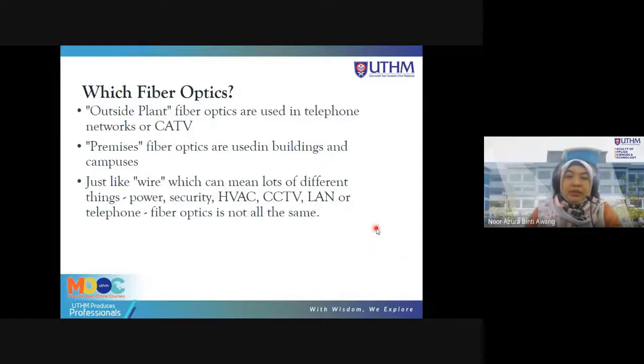So how do we install the fiber optic? Fiber is harder to install than a 100 megabit per second copper Ethernet cable, but fiber is much faster, so the infrastructure will not need to be upgraded so soon. Gigabit internet is harder to install over long copper cable. It only has a 20-pound pulling tension limit and can kink, which ruins the high speed performance. Fiber has more strength and greater tolerance to abuse than copper wire.